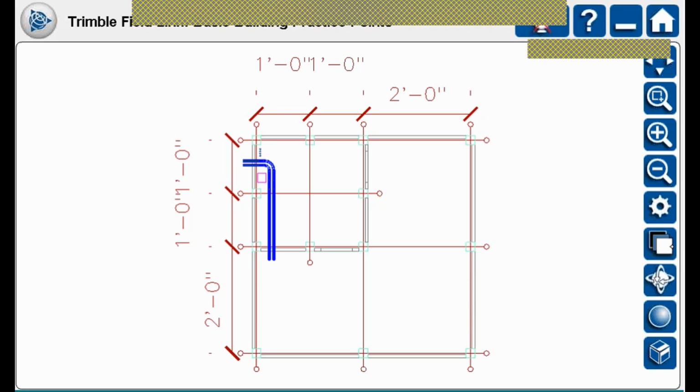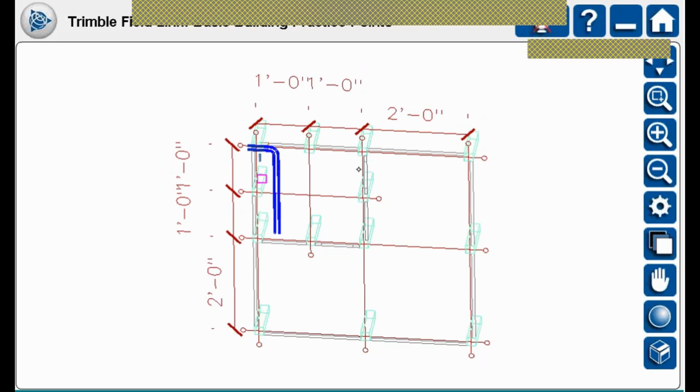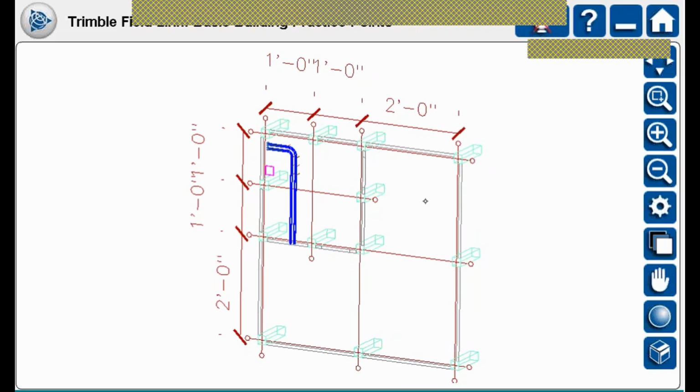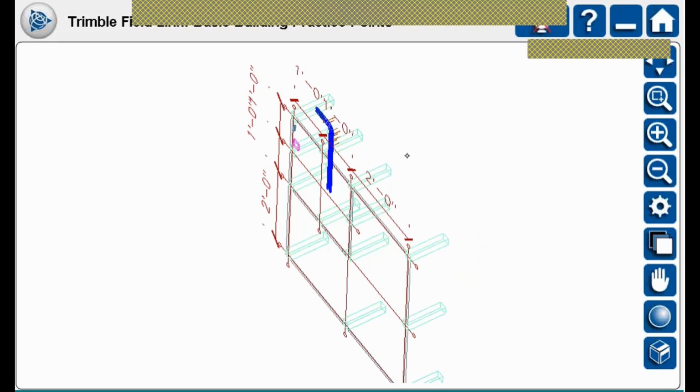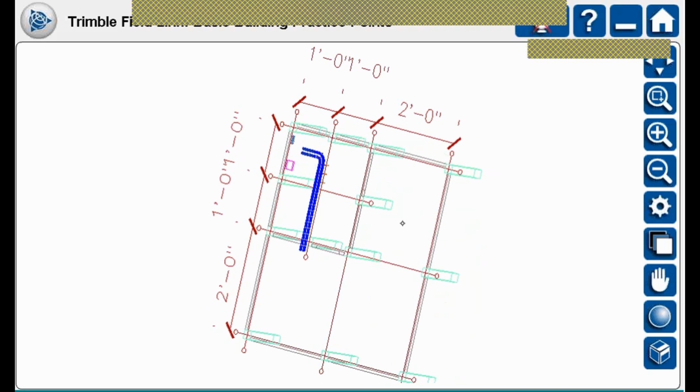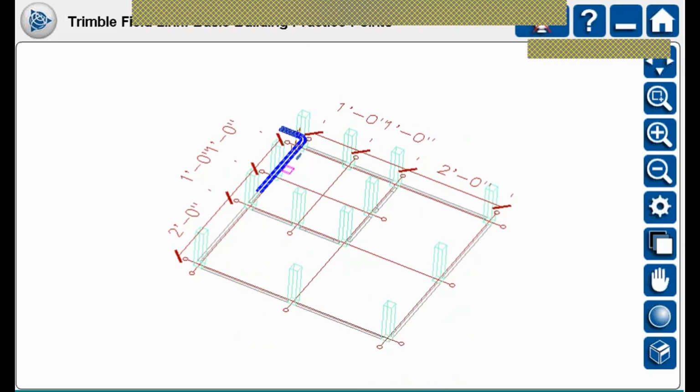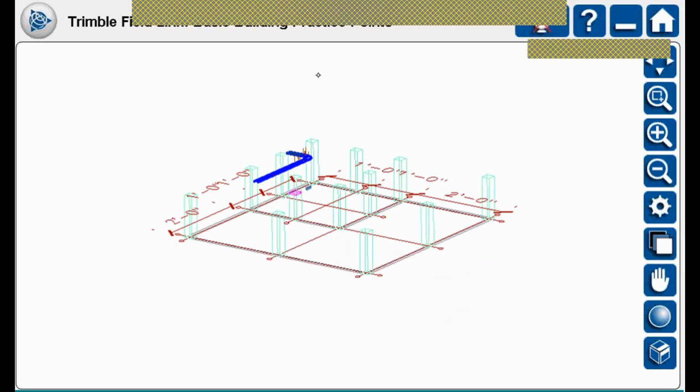Not too customizable, but there's a couple things there. The next one down looks like a little Earth with some orbiting type things going around it. That's exactly what it is. It's orbit. So if I click on that and pick in the center or anywhere in my drawing, I can start pulling this thing up to the point where I can see some 3 dimensions going on. However, this doesn't work as conveniently as, say, maybe the orbit in AutoCAD or Navisworks or Tekla BIMsight.